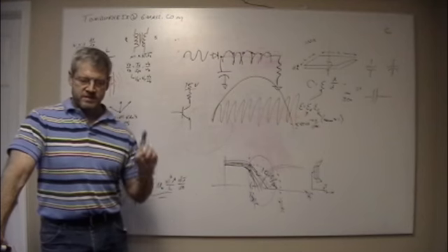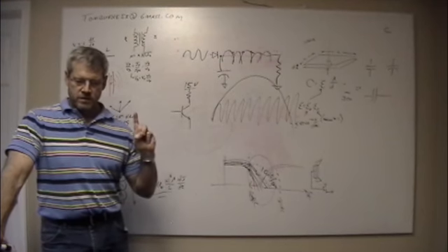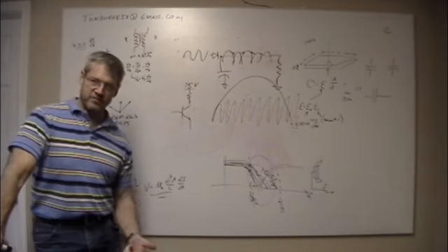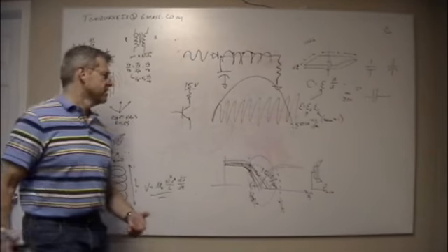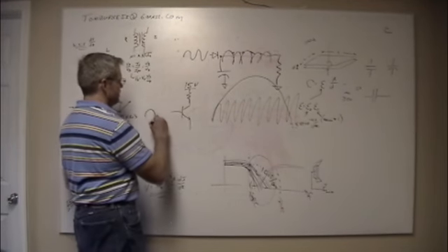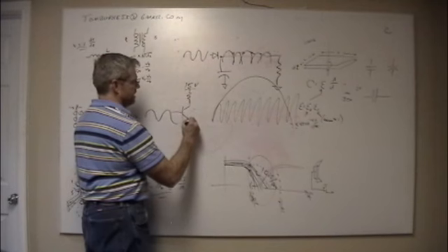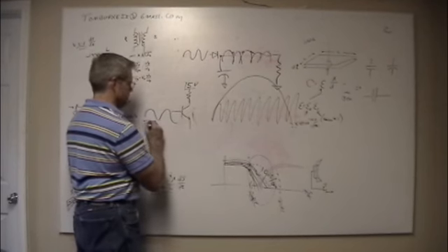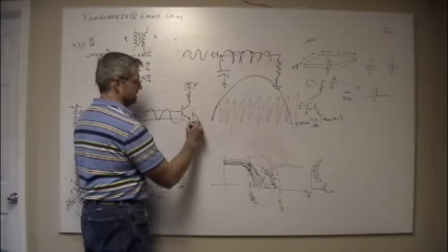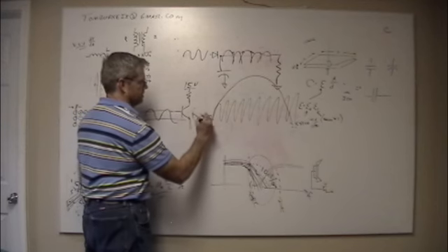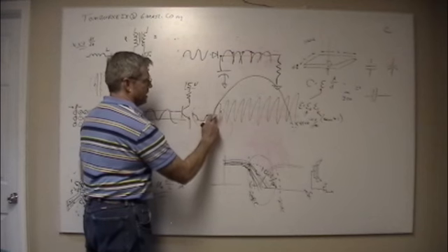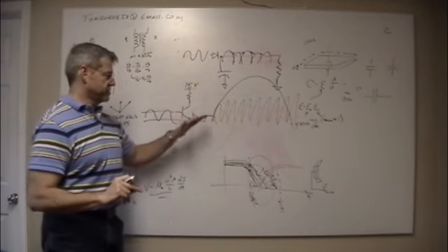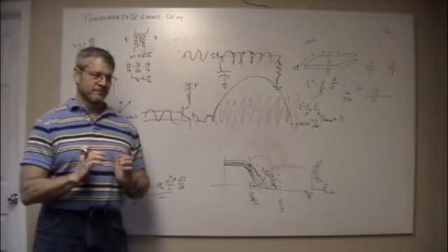The problem is that when you overdrive them and put in too loud of an input signal, which everybody does, on a transistor circuit, if I put in a sine wave, it chops it. So I get this thing that looks like this. So you're losing frequency response, correct? It's an odd harmonic. Okay. Because you're starting to approximate a square wave.